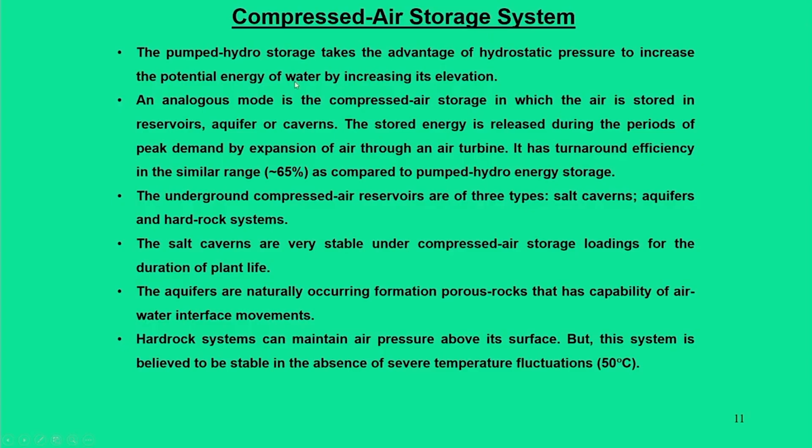Now, we will move on to the next segment of our discussion, that is compressed air storage systems. When you say pumped hydro storage, it takes advantage of hydrostatic pressure to increase the potential energy of water through its elevation. Now, the analogous mode in compressed air storage is that energy is stored in the form of air in a reservoir, aquifer or caverns, and this stored energy is released during the period of peak demands by expansion of air through an air turbine.